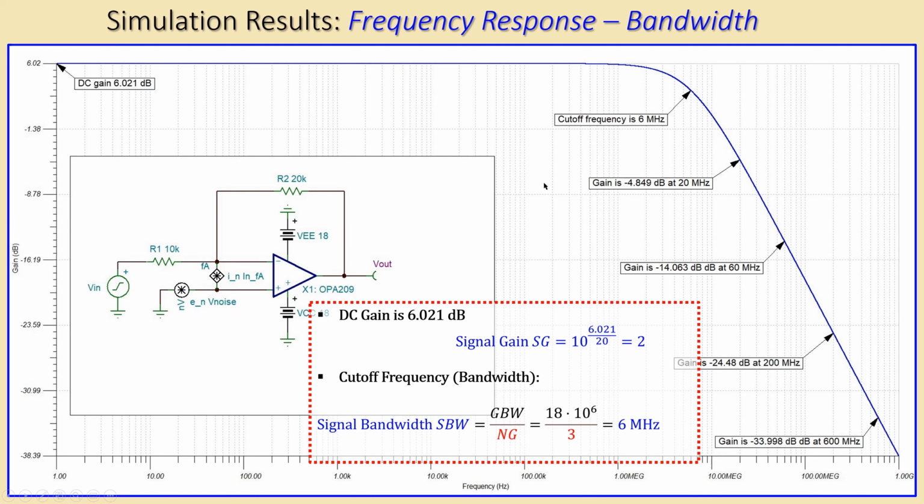We also had an assumption that our system will behave as a first order system, and then specifically a first order low pass filter. But we need to of course check that. How can we check this? Now let's look at the labels here. We have several labels. We have 20 megahertz here, and it has a value of the gain of approximately minus 4.85. If I go 1 decade above with my frequency, so I will make this 10 times larger, it will be then 200 megahertz. I need a decrease of 20 dBs. Is this correct? Let's check that. So this is now minus 4.85 dBs, and I need actually minus 24.85, which is very close, not really precise. So it is very close to that one.